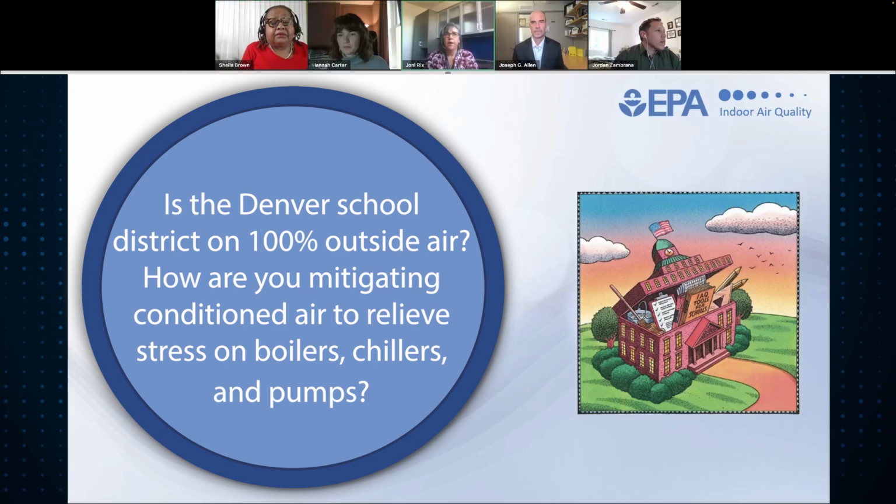Yeah, Colorado is tricky because we can have such massive swings in our temperature. It's very dry here, but it could be 70 degrees one day and then it could be really cold at night. So within that, our HVAC shop has set very specific parameters that they try to keep the boiler between 68 and 72. It runs from the months of October to May. And then if they have air conditioning or chillers, then those work at the other time, basically summer through early part of fall. Hopefully that answers. Thank you so much, Joni.